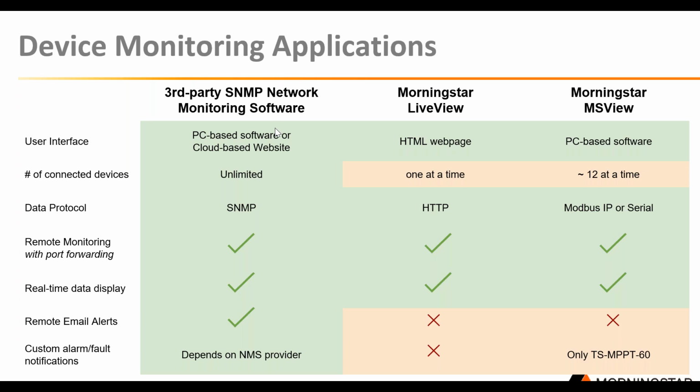And how that compares to our existing monitoring platforms, those being Morningstar LiveView, which is, again, supported by the HTTP protocol. It's just an HTML web page that is hosted locally on the device. Just serves up a web page with real-time data display.